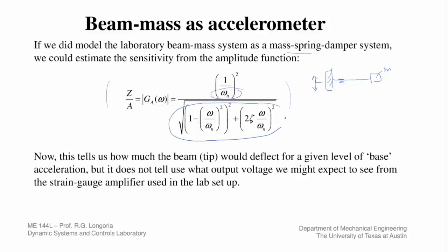The numerator and the denominator just tells you, if you plot this versus the forcing frequency that you're actually vibrating the base at relative to the natural frequency, and let's say that that's 1 here, where those are equal, as long as I'm operating down here, then this value here is a constant, and it's basically 1 over omega n squared, isn't it?